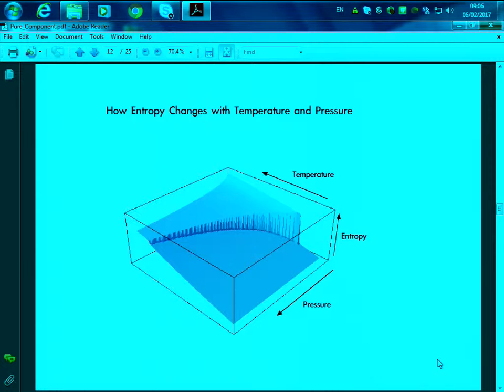What is this line that we saw last time? What does that line mean? This curve. This is change of phase. So here, this is the saturation curve or line, what we call. And basically, we're moving from, what phase do we have on this side of the chart? Liquid phase to a gas or vapor phase, right? And here, what do we have? A step change in the entropy.